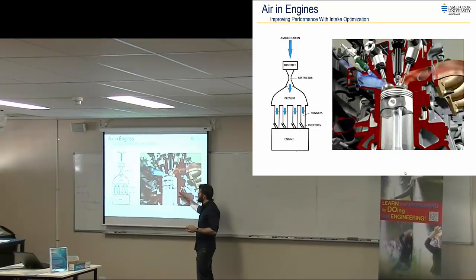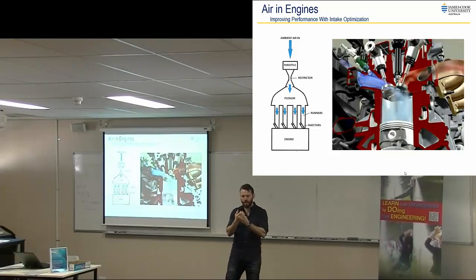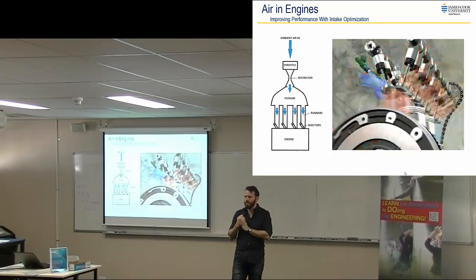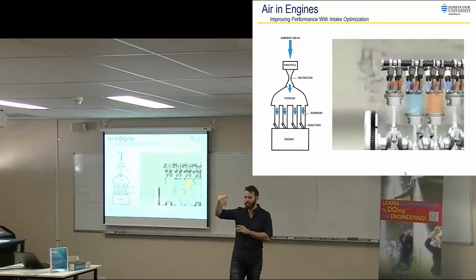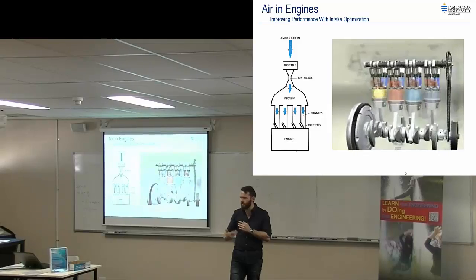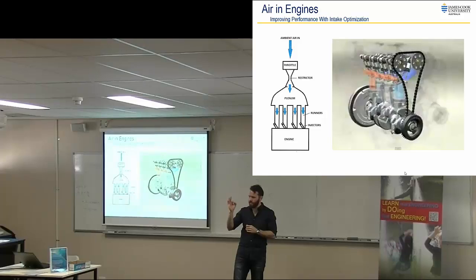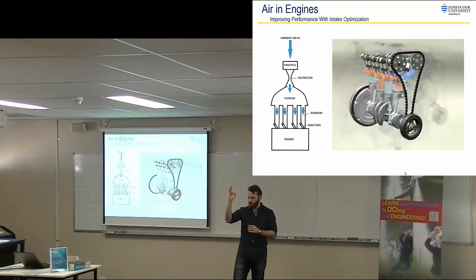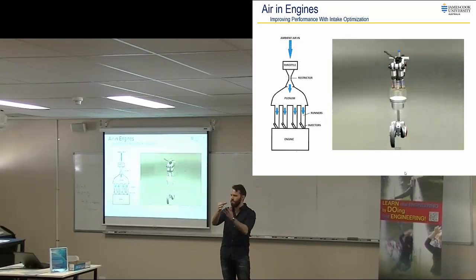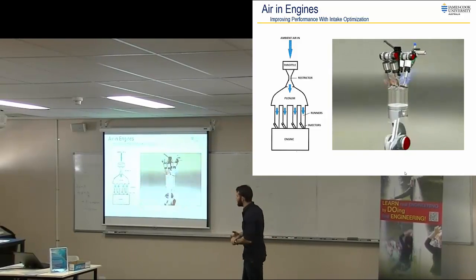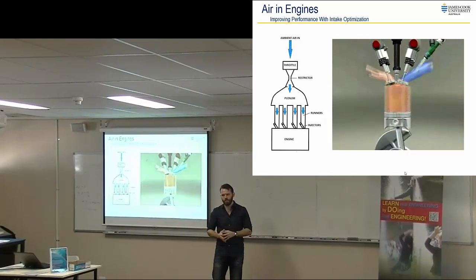So when we actually have combustion in an engine, you need three things. You need spark, you need fuel, you need air. And when you put your foot down on the accelerator, the only thing you're doing is just opening up a valve that allows more air into the engine. And the more air that goes into the engine, the more it burns and the more power you get. Okay? So when you actually put a restriction, and on these cars there's a 20 mil restriction on that intake, so you've got a hole of 20 mil that 4 cylinders worth of air has to go through, you've got to optimise a lot of the air flow in that intake. And so that's what these students are actually doing with simulation and experimentation and all sorts of things.